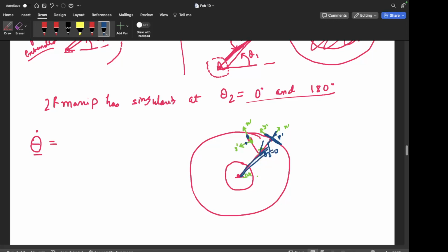So at this very specific position when theta 2 is 0, you can only move in one direction, right? The p dash point is not reachable. And since this is a 2D plane and one of the directions is not accessible to you, that's why I said that the manipulator has lost 1 degree of freedom. Yes, sir. Okay, sir. Clear, sir. Okay, cool.